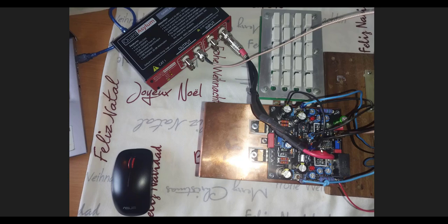We have some nonlinear behavior inside the amplifier. We have PSR. We have a lot of perturbations that go inside the amplifier. This is not an optimized, let's say, ideal circuit. We have crossover distortion. We have a lot of perturbations, and these perturbations in a closed loop system are attenuated by the open loop gain. So we need to have a high open loop gain to reject these perturbations and have a very good THD,